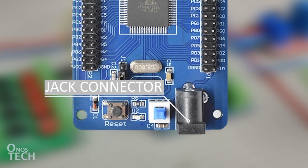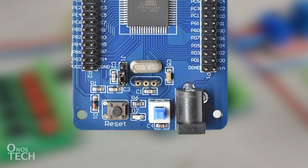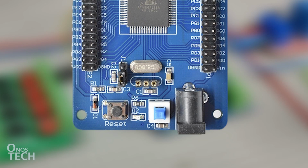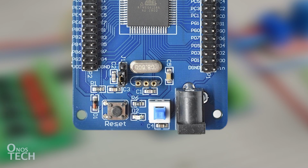Below is a DC jack female connector and a switch for 5-volt power supply to the board. Here is the microcontroller reset push button switch. A 16 MHz crystal oscillator is plugged into this pin slot. The J1 jumper selects between the onboard and the external crystal oscillator.